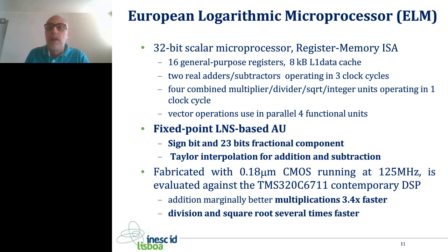So I'm not going too much into detail. I will give you the general picture. It was fabricated in 180 nanometer CMOS technology, running at 125 megahertz, and is evaluated against the DSP from Texas Instruments, the 320C7700, which is also a contemporary DSP.